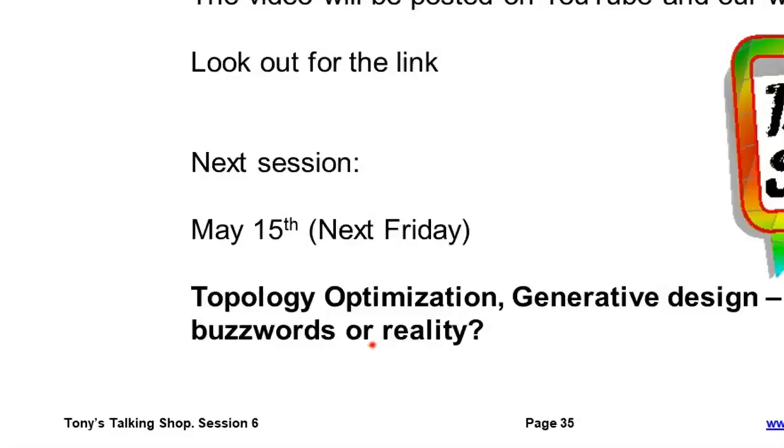Badri has a question. Random vibration fatigue based on Miles' equation is linear. The assumption here is that the vibration fatigue is high cycle. What happens when the stresses are greater than yield? Is there a way to account for that? Yes, as I mentioned before, we're interested in the cycle count for high cycle fatigue, and also indeed for low cycle fatigue. The rate of loading we don't take too much account of, but that breaks down if we actually have vibration fatigue, and that's where the dynamic effects, the inertia effects, come in.